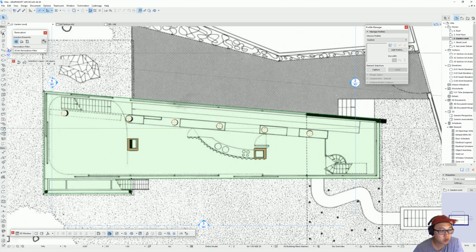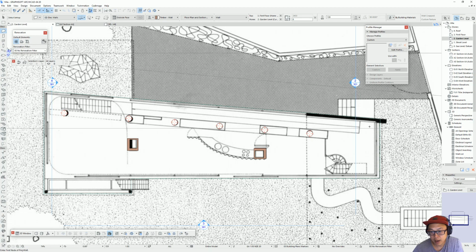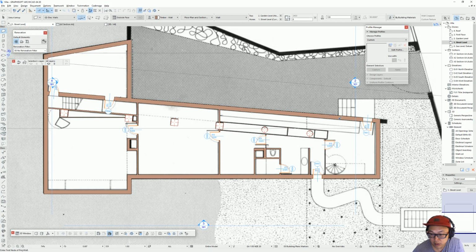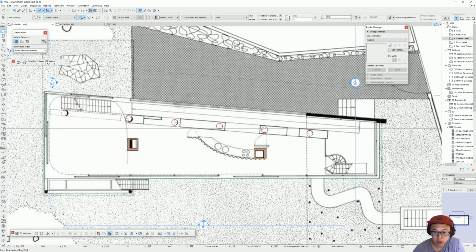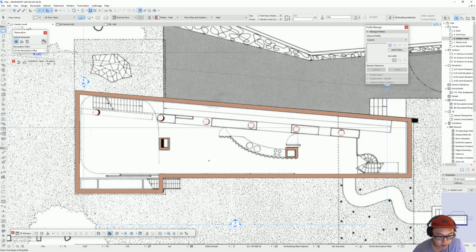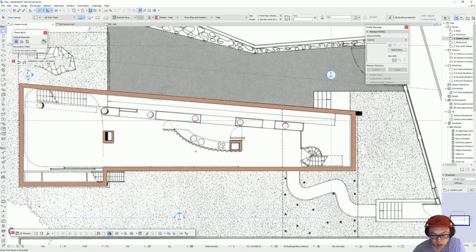We're gonna take the wall tool, and now it's the same size as this. I'm just gonna take that, absorb the properties of that wall, go up, get the wall tool selected, press spacebar to get inside that slab, and now you get a perimeter wall.